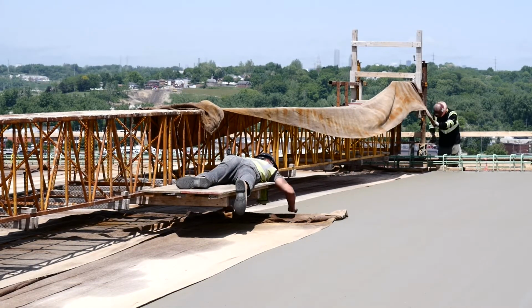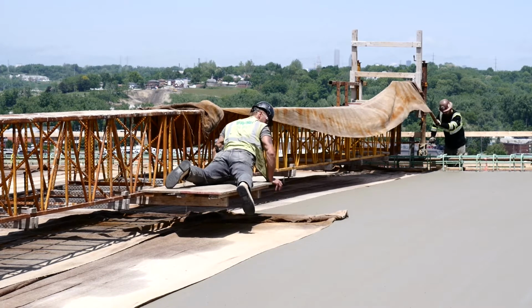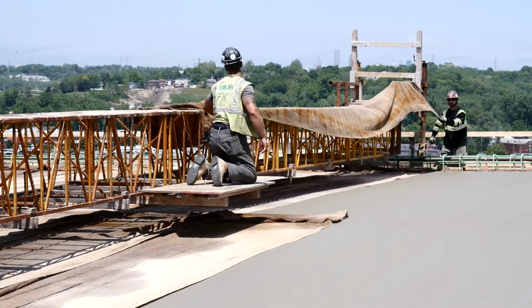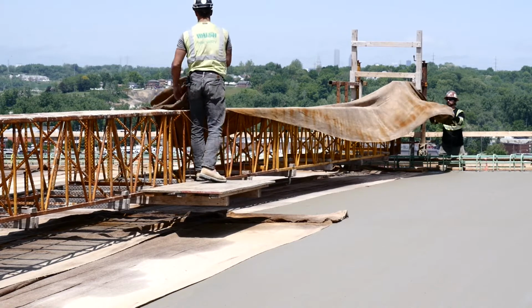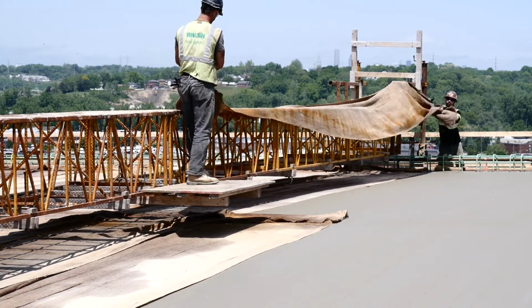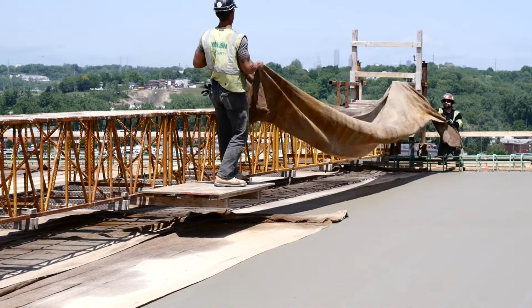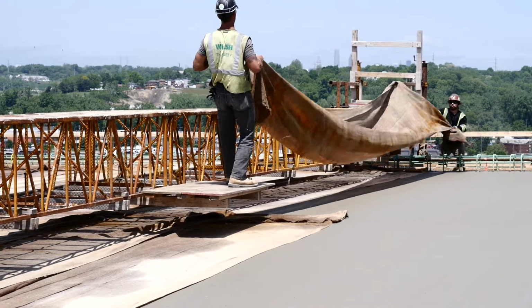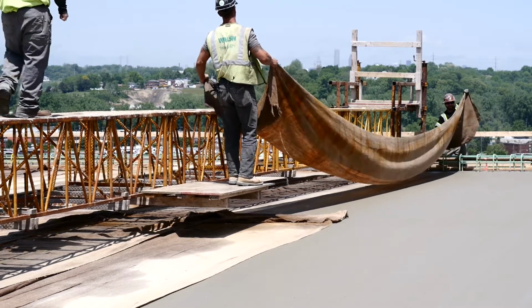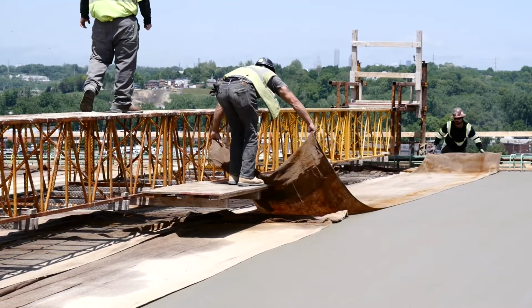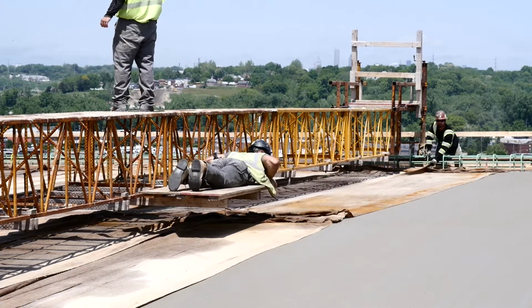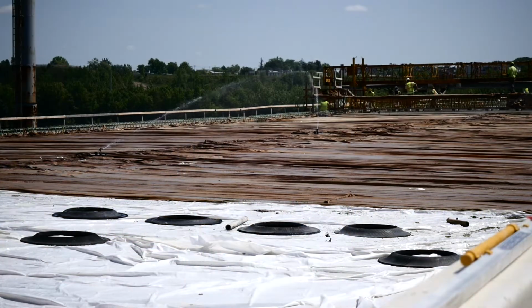So you may notice out on certain construction projects that once the concrete is placed, we have burlap that's put down on the concrete, and we have hoses that run across. And that is our process of curing the concrete. So it sounds a little contradicting to actually keep concrete wet in order for it to harden and cure, but the process of having the water with the concrete helps with the hydration, and it is crucial to the curing process. If the project does not have properly cured concrete, that can also result in premature failures as well.